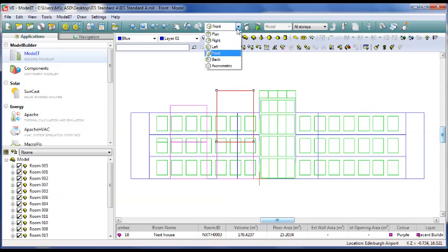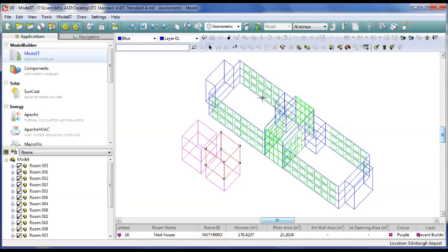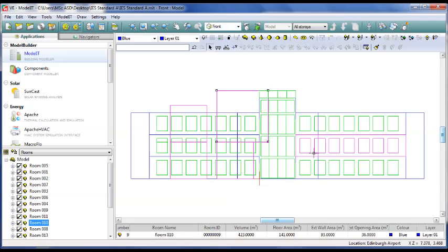If I now go back to axonometric, I can also extend that in one direction or another. This works in plan as well. I just have to select one of the sides after selecting the button at the top there, and then drag again, and it says in steps of a meter how far I want to move it, so I'll just do that, and it's given me a cantilever off the front, as you can see.